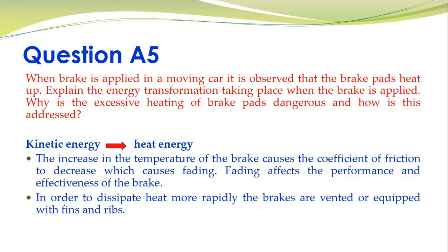In order to remove this heat, the brakes need to be vented. Ribs, fins and vents are provided on the rotor itself. The brakes are not finned, right? The brake pads are not finned, but the rotor that is attached to the hub has ribs, fins and holes in it to provide air circulation. As the air moves past the brake pad, it cools it quite effectively and removes the heat quite effectively.